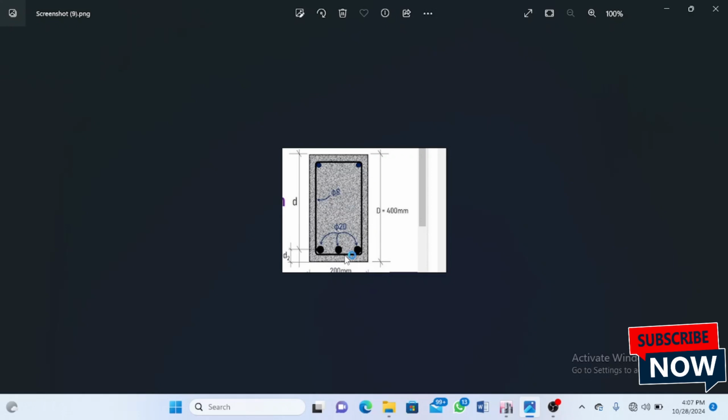This is a stirrup or a link, depending on if it's a beam or a column. If you don't really know how they look, these are it. It's just confinement bars that are around the beams or columns all over, maybe at 200 center to center. These are the stirrups.